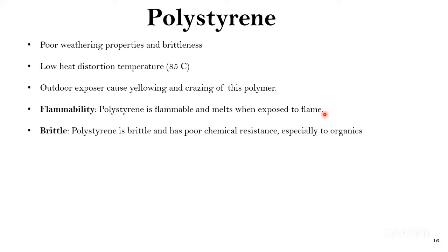That polystyrene might include some kind of additives or fillers, flame retardant fillers, so the flame retardant tendency is high in that case. Another property that may disappoint in application: if you expose this polystyrene for a long time to sunlight or UV rays, you will find it becomes very yellow in nature.